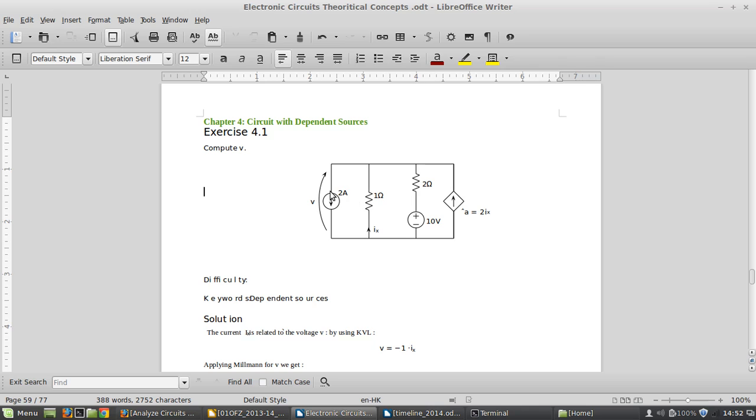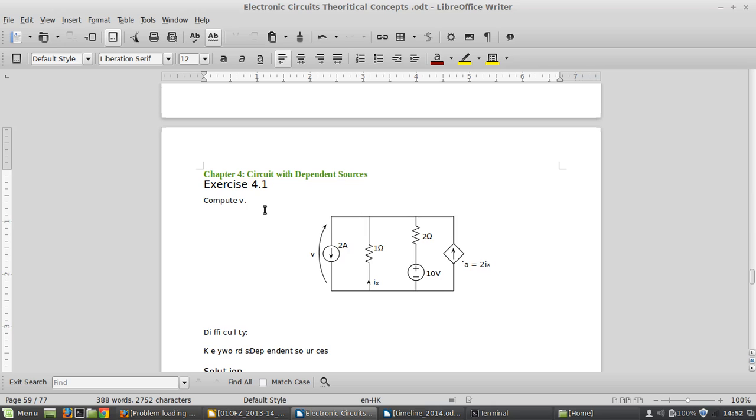So these are dependent sources, and you can check out that this is an independent source because it doesn't relate with other kinds of sources. But this dependent source is related with other sources. That means you can check out its ix. The value of a dependent source is dependent on this variable, that is ix, and ix is somewhere else present here. So this dependent source is totally dependent on this current ix.